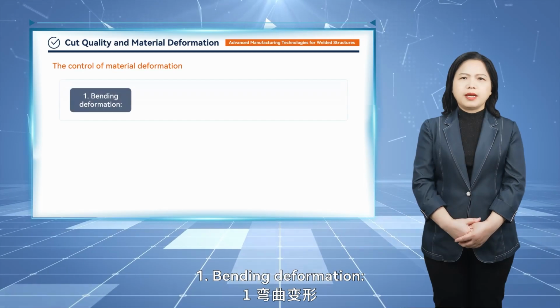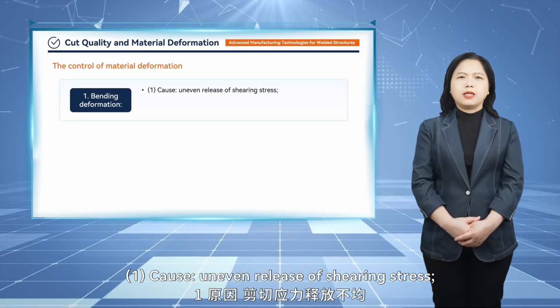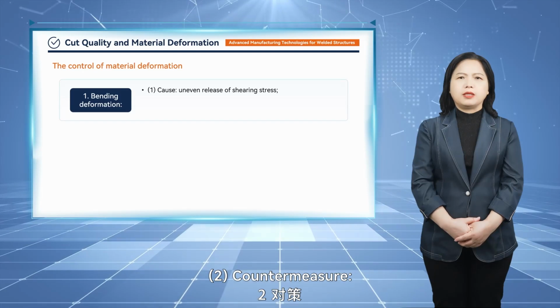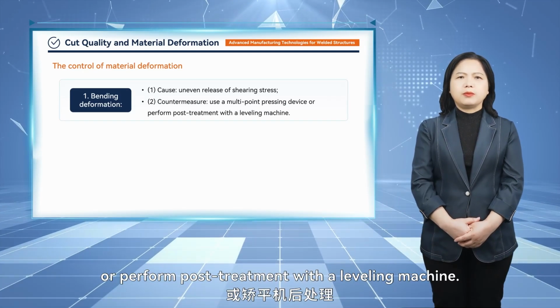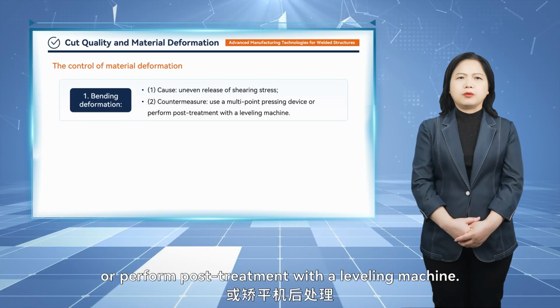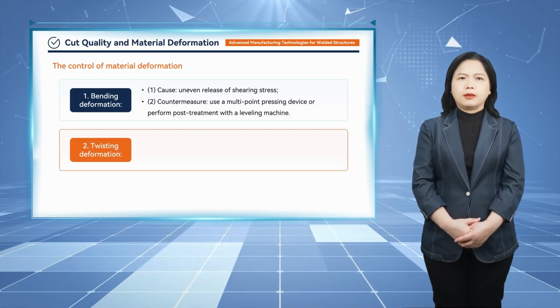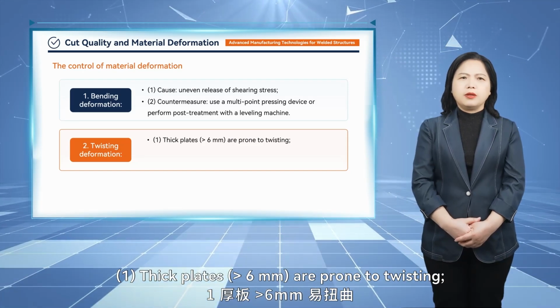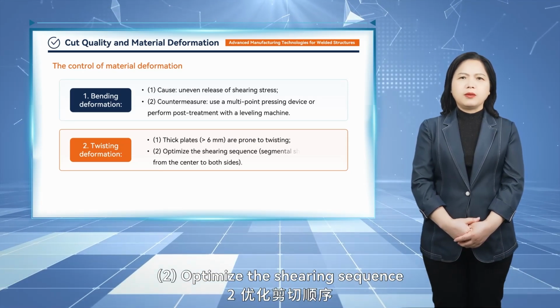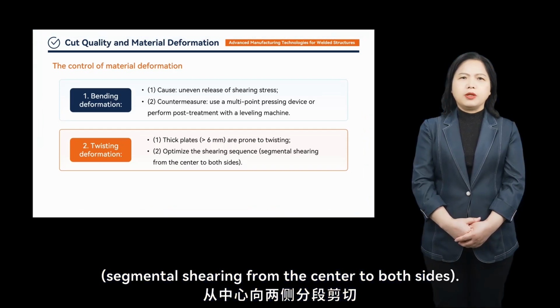1. Bending deformation. 1. Cause: uneven release of shearing stress. 2. Countermeasure: use a multi-point pressing device or perform post-treatment with a leveling machine. 2. Twisting deformation. 1. Thick plates, greater than 6 mm, are prone to twisting. 2. Optimize the shearing sequence. Segmental shearing from the center to both sides.